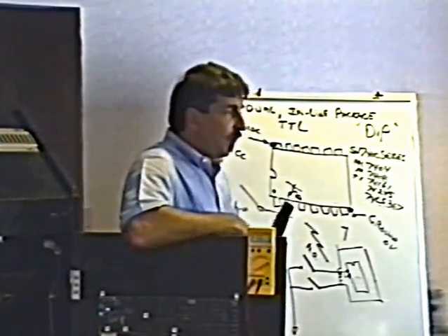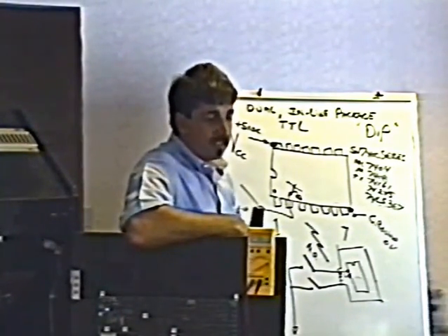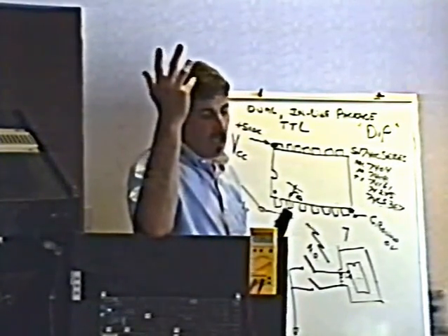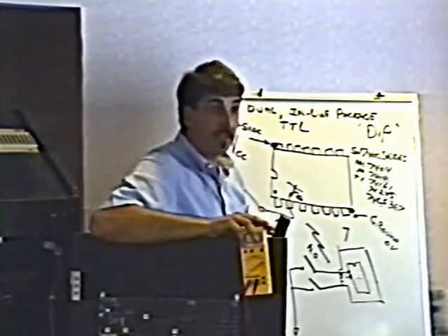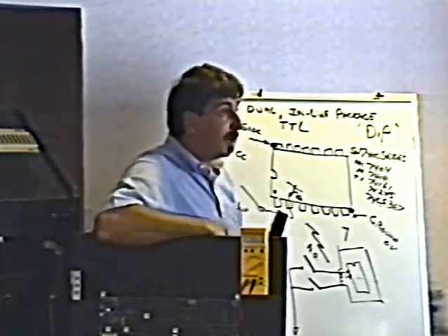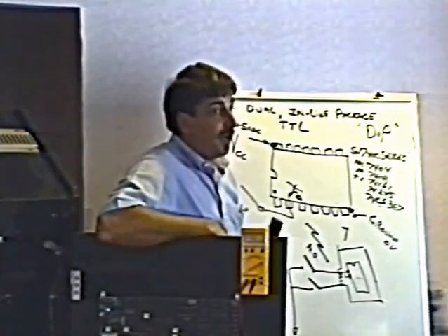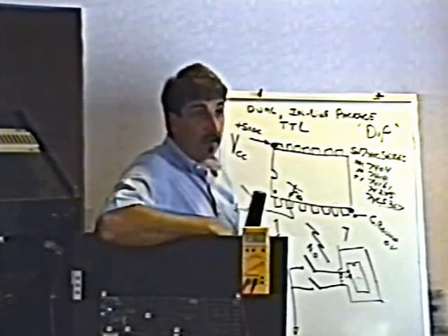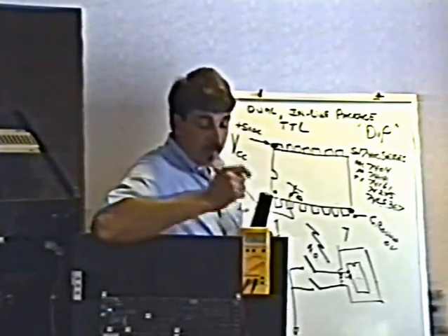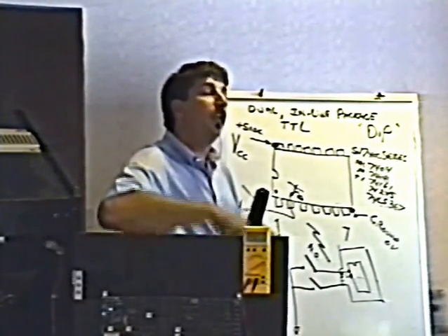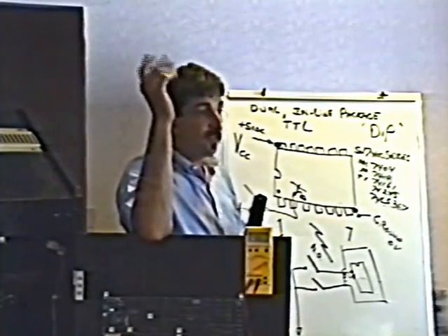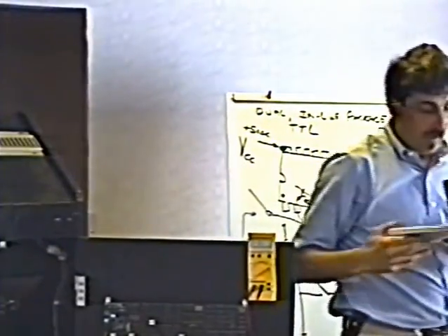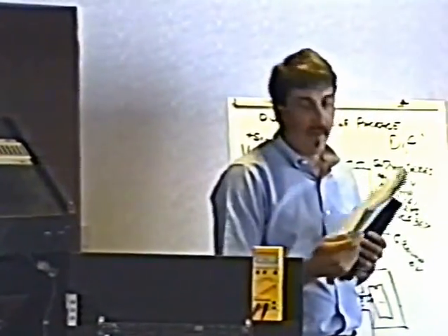That is, what most of the hotshots will do when they have a problem like this is they'll sit down with the oscilloscope, they'll power it up, and they'll start probing around all the pins of the ICs, which requires that you know how the IC works and everything, and you have to know what's going in, what's coming out, and all that stuff. I don't even do that anymore. When I have a board problem, and especially if it's an input failure or an output failure, this is what I do instead. Put the meter on diode test, ground the red lead, use my black lead to probe the pins of the IC. And this article tells you step by step how to do all of that stuff.